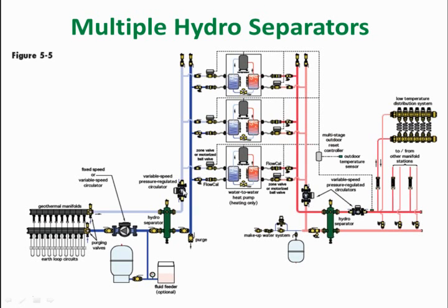Same thing here. We're using a single pump system. We've got zone valves on both sides of the heat pumps here, both coming from the source side into the heat pumps and going out on our load side. We've got it zoned with valves.